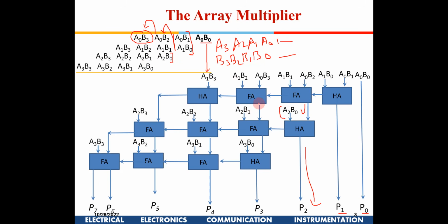Okay, and I have used one full adder and a half adder here. So there could be a carry here or here also. It doesn't matter. All those carries need to be catered to in this stage. But obviously our building block is a full adder, which can have a maximum of 3 bits. So you can't do addition of so many things in one go.